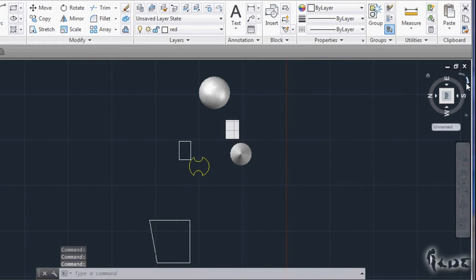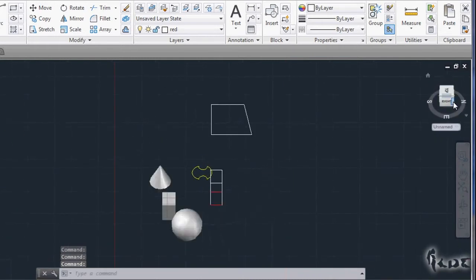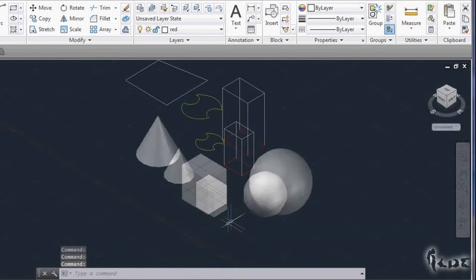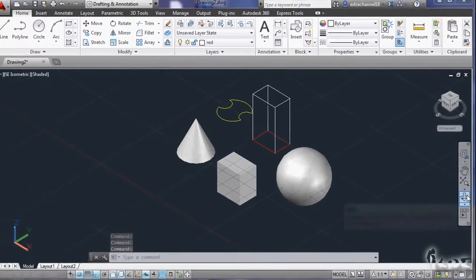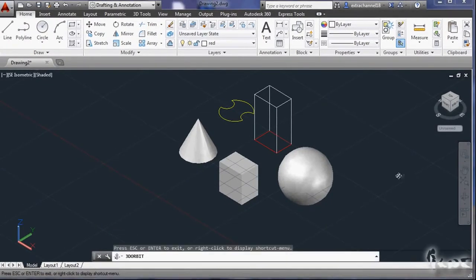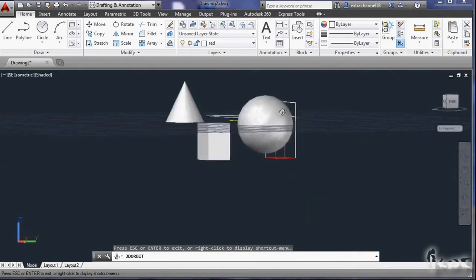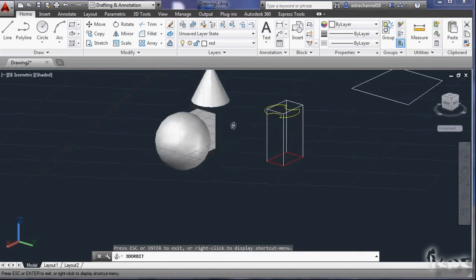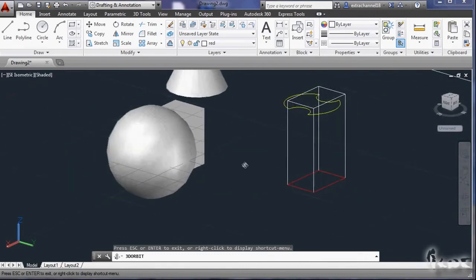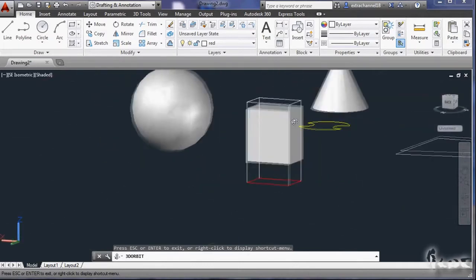You can further click on the vertices and edges of the cube to watch at your project from odd angles according to axis directions. The orbit command on the extreme right lets you move the point of view with total freedom. Press then Escape from your keyboard to exit from this action as always. Use it to check, for example, if solids drawn are all aligned. Zoom in and out using the mouse wheel.